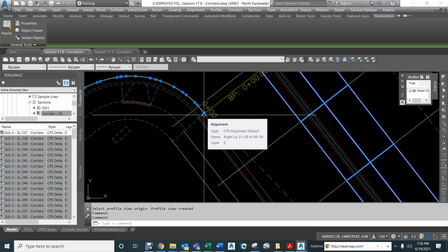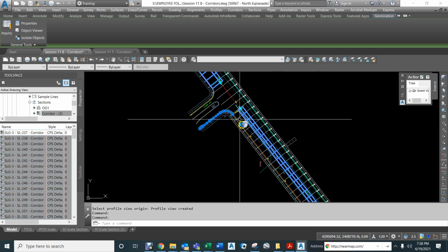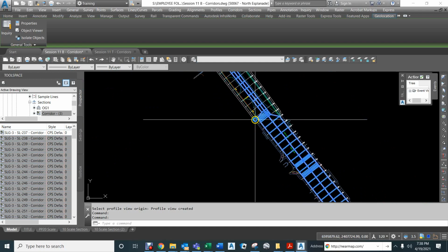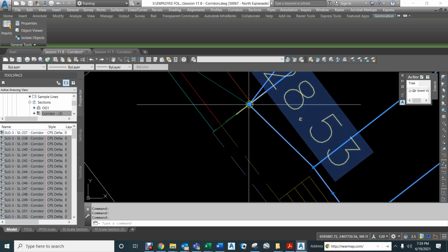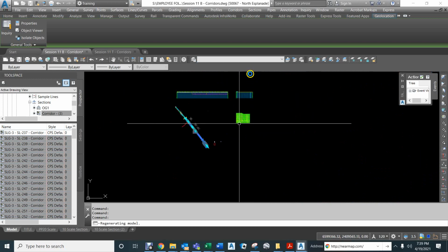So it's 170.43 at basically zero elevation in the new profile, in the new alignment. And then it's going to go down to here, and at the end we want to be shooting for a 169.11. So as a starter, that's where that profile needs to be.